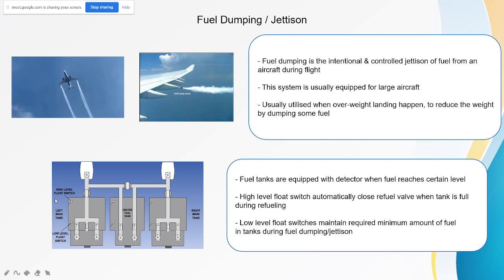But here we can also see a high level float switch. This is usually equipped on all aircraft because it is used to automatically close the refuel valve when the tank is full during refueling.